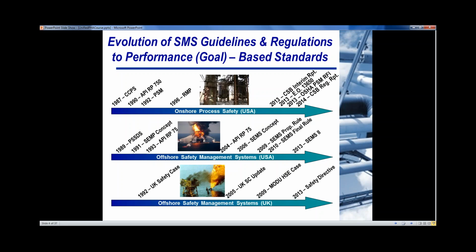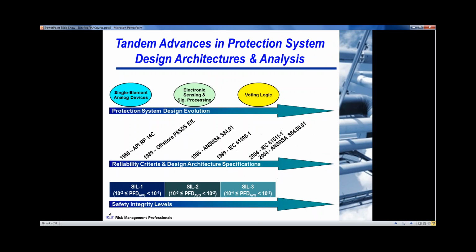And a key part of process safety is understanding the hazards. Realistically, the HAZOP and, more recently, the LOPA have been tried and true tools for evaluating hazards. They've been shown to be effective. They're endorsed methods. And although nothing's ever 100% in life, the fact is they do a very good job of cost-effectively flushing out potential weaknesses or vulnerabilities in design or operations. So from the standpoint of protection of life, protection of the environment, and protection of property, identifying hazards properly is important. From that perspective, HAZOP and LOPA quality is important.